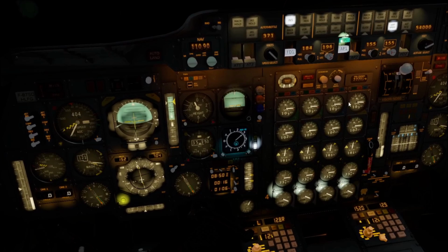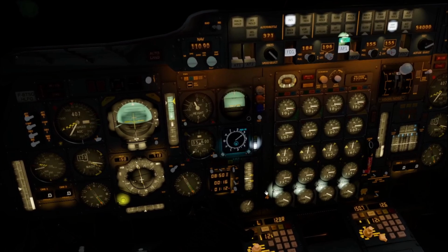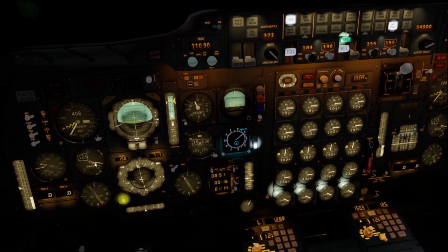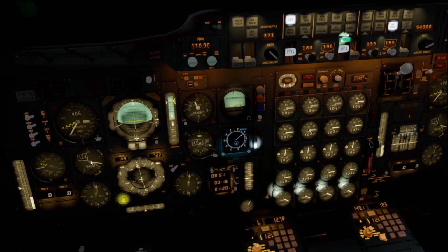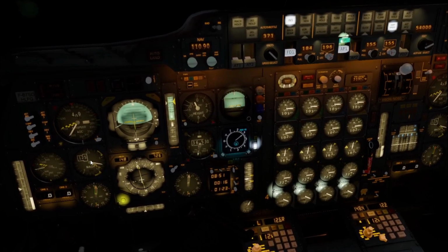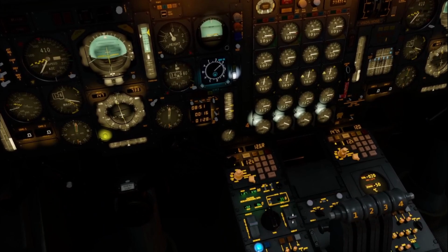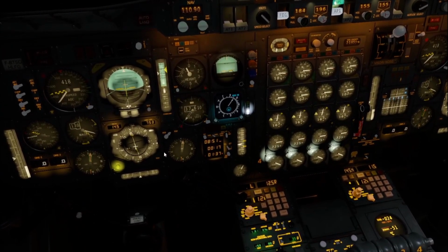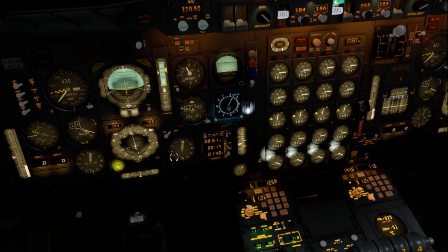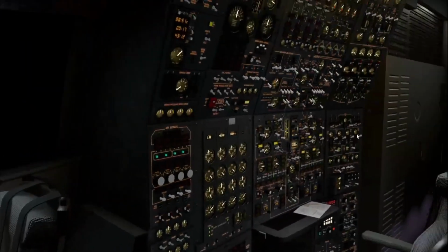And with this very light aircraft, we can probably shut off the afterburners very early. So let's leave it at least 1.7 is normal procedure. We can do this at 1.50. I will limit climb rate to 2000 feet per minute to gain speed. And if your speed is not getting higher and higher, as an extra procedure,